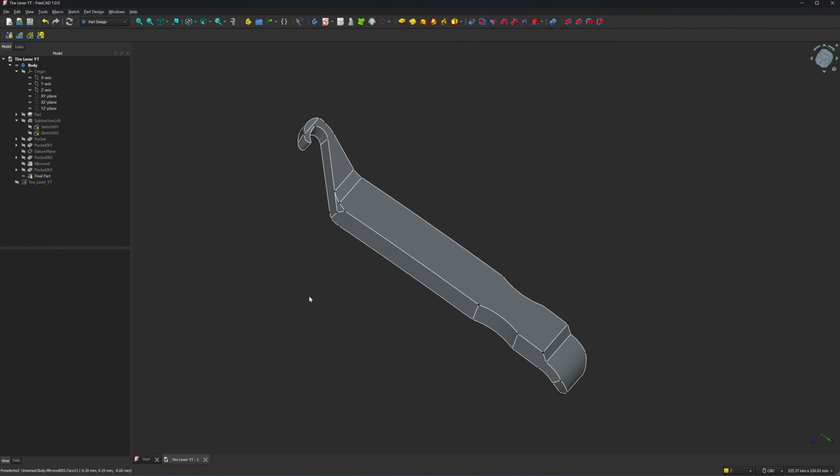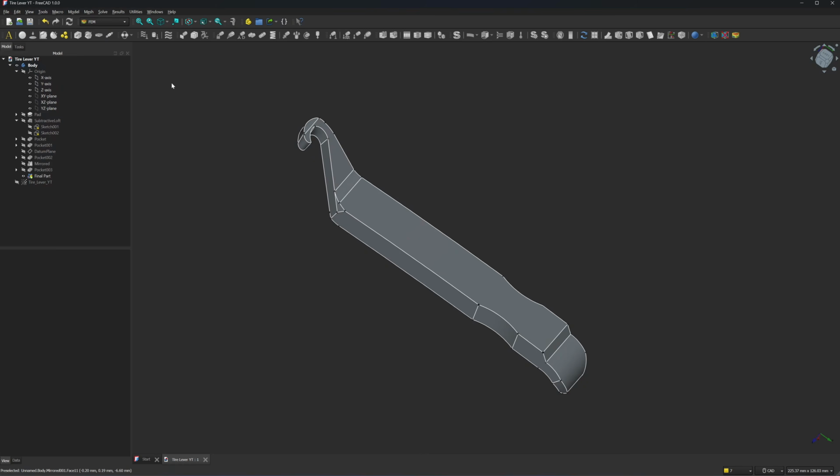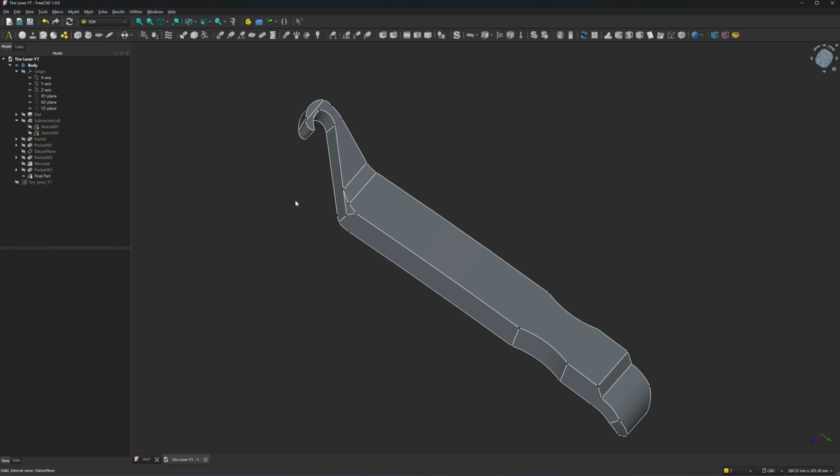Okay, FreeCAD has a feature called FEM, Finite Element Method. This will allow you to find out when force is applied to your design part, when it is going to break and how much it will deform. So you can predict and simulate with this function so that you can design proper stiffeners, thickness, and also the shape of your object to sustain a certain load.